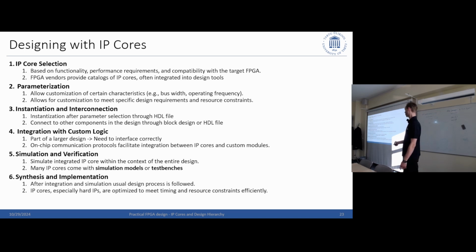And of course, now the block is just hanging around on my FPGA. My synthesis tool will immediately throw it out again because it's not connected to anything. I will need to connect it to other components in the design through block design or an HDL file, depending on which approach I prefer.